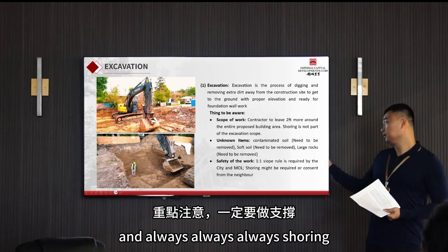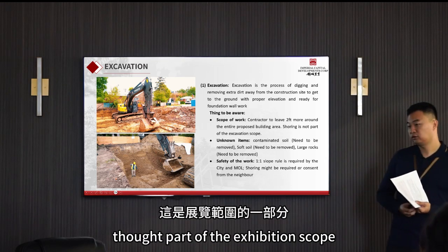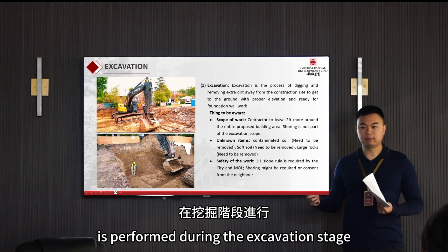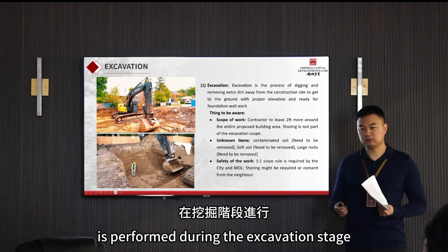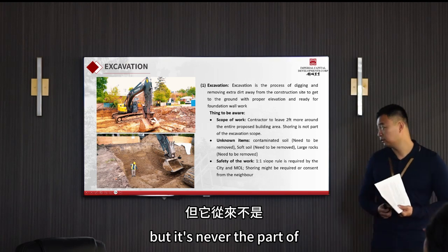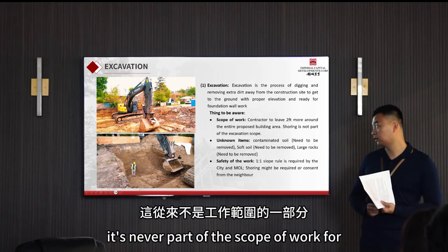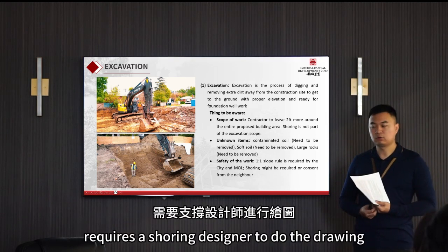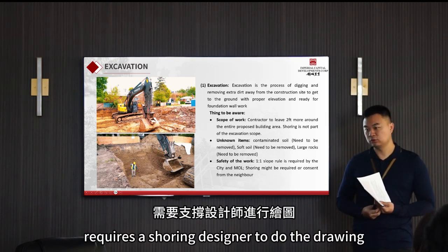And always, shoring is not part of the excavation scope. I know shoring is performed during the excavation stage, but it's never part of the scope of work for demolition and excavation, because shoring requires a shoring designer to do the drawing.